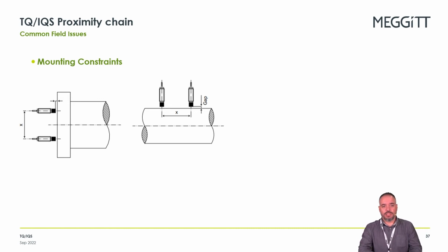It is also important that there are no other sensors below the recommended distances. Not only would the magnetic fields of each sensor interfere between them, but also the magnetic field generated by the eddy currents in the target would interfere between them. These distances are mentioned in the installation manual.